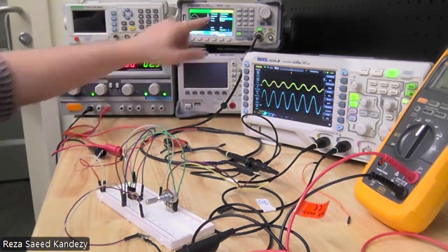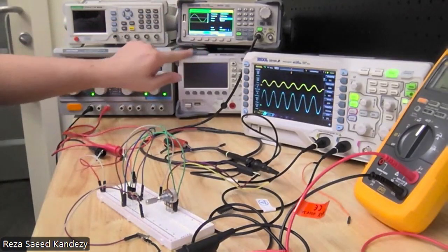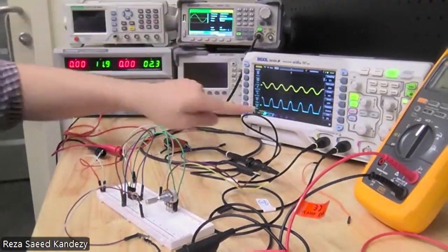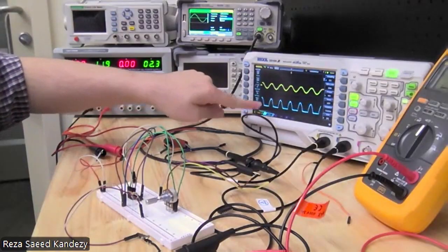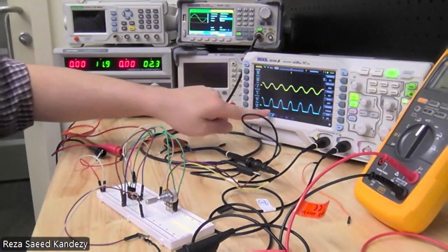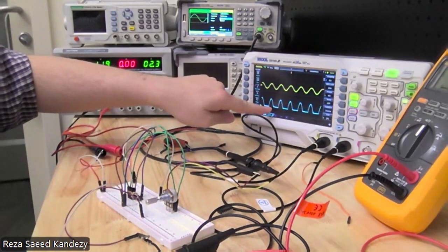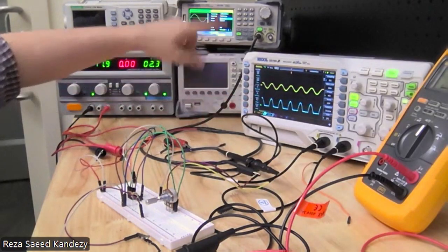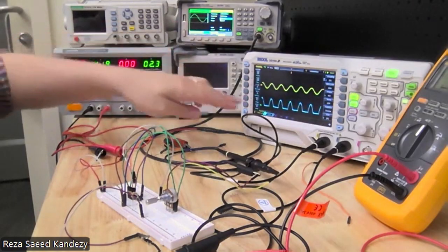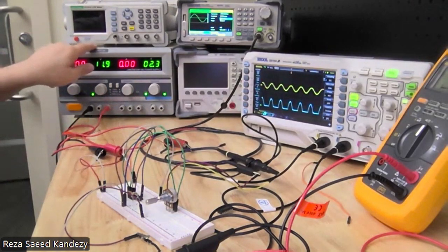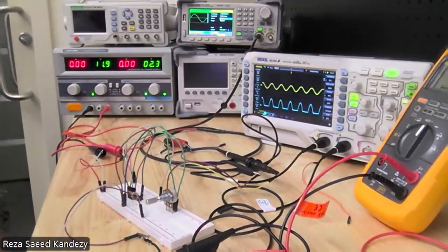Now, let's talk about the input. I said there is an offset. Now, I'm going to change my offset to 0. Okay? Now, you can see that because I have negative half cycle, it gets chopped down. This is the point that the input crosses the 0 line. So this is what we meant when I said you need to always have a positive voltage in your input, and your supply should be big enough to support the voltage that you wanted. Okay, now let's move on to the next.